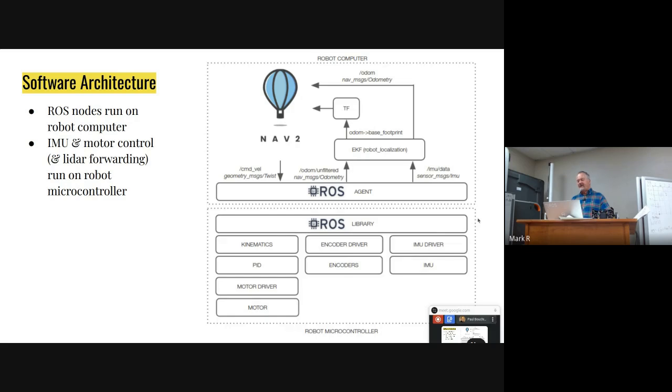For the Wi-Fi configuration, there's a separate piece in the firmware that takes the serial off the LiDAR and pumps it up outside of the ROS environment, outside of ROS messages or anything like that. Just pumps it up through a UDP socket to the laptop. If you're running on the robot, then it would plug into a serial port on your robot computer, on your Raspberry Pi.